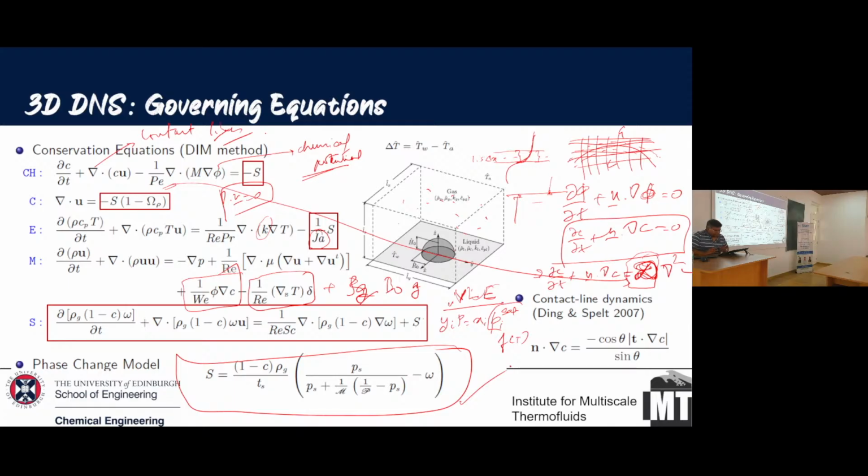I'm going to come to the drawbacks. The first assumption I have made here is that I'm using a vapor-liquid equilibrium model. In an evaporation system, when you consider vapor-liquid equilibrium, it means this is a very slow evaporation. At each state, we assume that there is equilibrium between vapor and liquid.